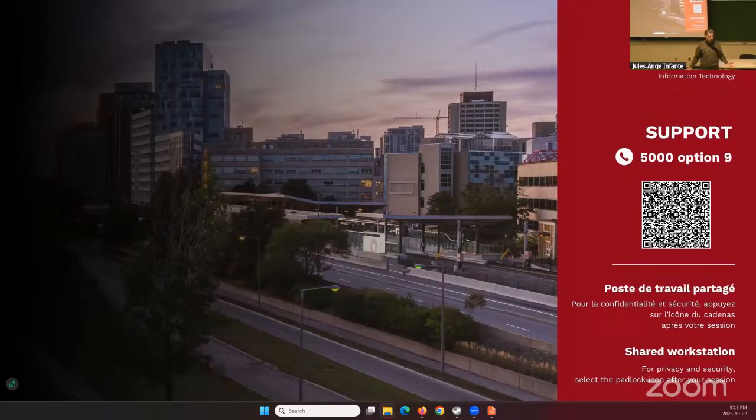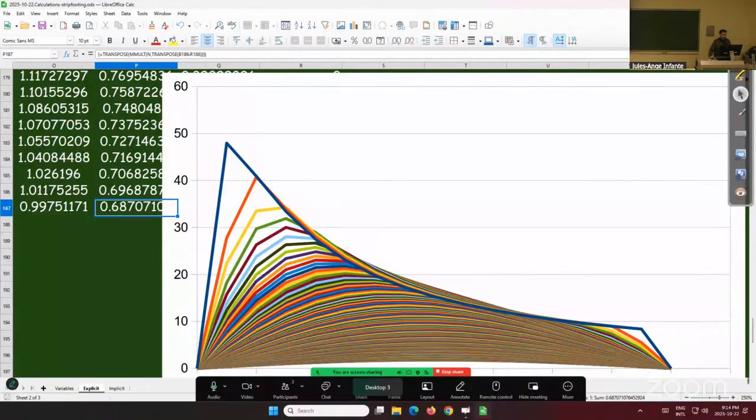But the thing is, when you are doing an excavation, you're reducing stress, right? So over time, you should expect your clay to lose strength, because pore water will migrate, because you've removed the loading, you get the suction. Remove loading, and all the change in total stress is instantaneously carried by the pore water pressure. That's why here we used as our initial pore pressure, right, at time zero.